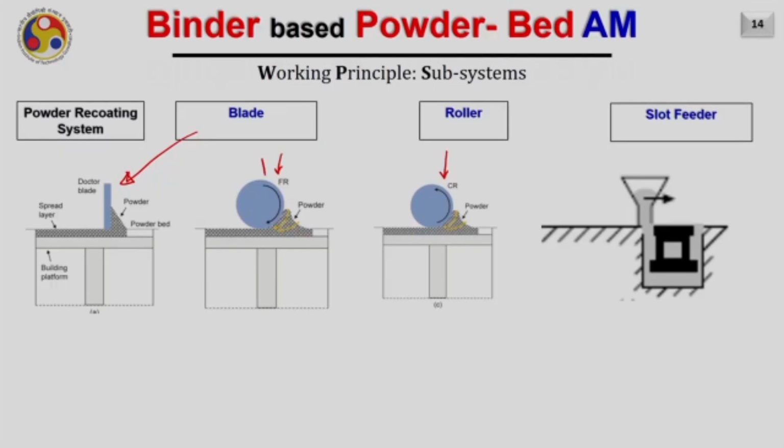If the part's green strength is very bad, meaning there is very little binder, then it may break even when you take it out from the machine itself. Therefore, there should be an appropriate optimal value of the pack density which you are spreading. If you are using forward rotating rollers, then they will push the powder material downward and increase the pack density of the deposited material onto the powder bed.